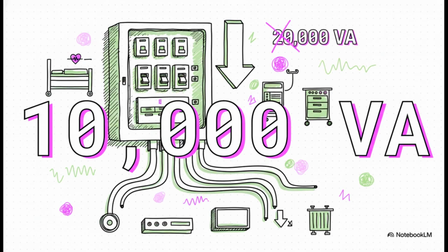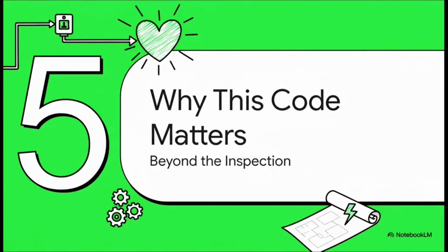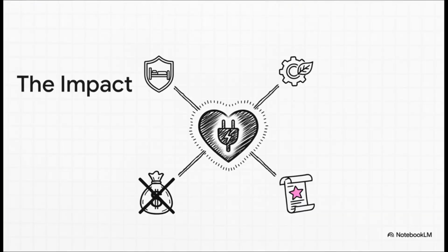That 50% floor is the key insight. The code is demanding that even after the initial load, you have to assume at least half of the remaining outlets in a critical care space are active. And that means? Larger wires, bigger panels, and maybe a much larger generator for your emergency power supply to that part of the hospital. So if an engineer messes up and calculates a Category 4 operating room using the Category 2 table, it could be a disaster. That 25% factor could lead to a catastrophic overload right when life support or an anesthesia machine is plugged in and running. That is the exact risk.